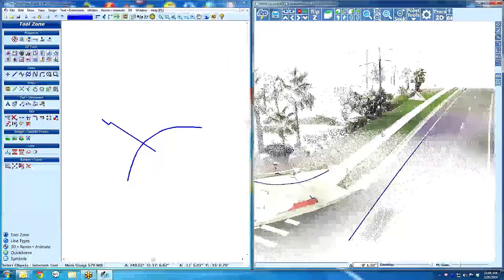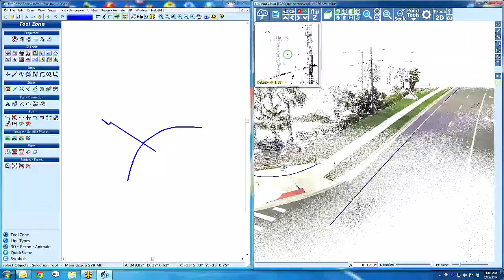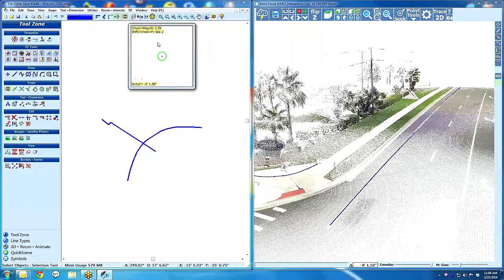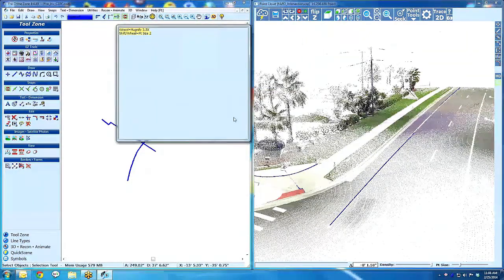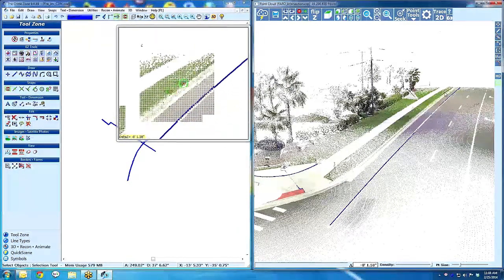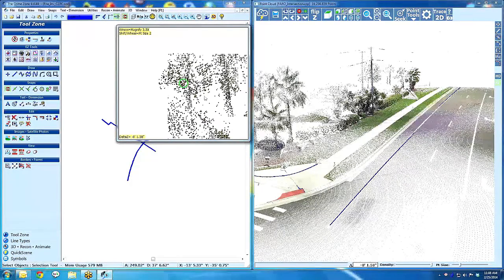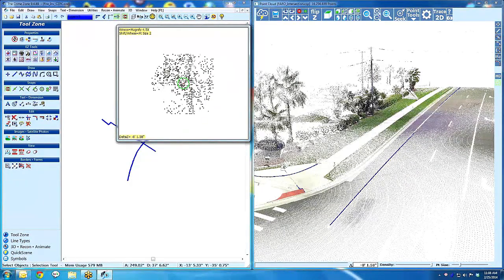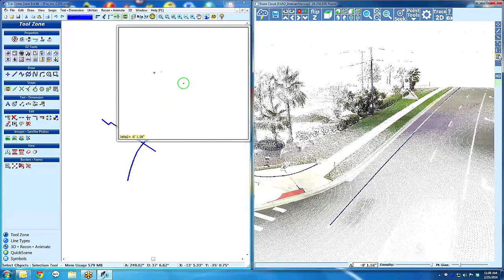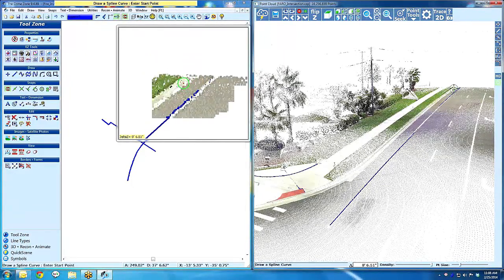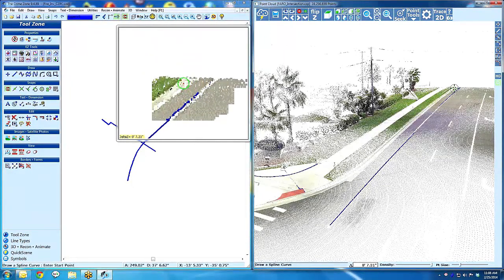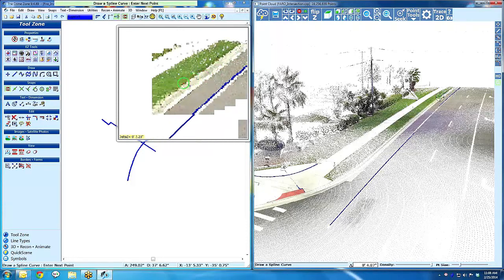So what we did was we came up with our mag window. So you click on the mag view window, and you can make that even bigger if you want, move it around. And you can see it is set up to a magnification of 3.5. I'll set it up to 4.5, and I'll thicken up the points a little bit with the mouse wheel. It shows you what to do. Shift and mouse wheel changes the points. Start a curve.